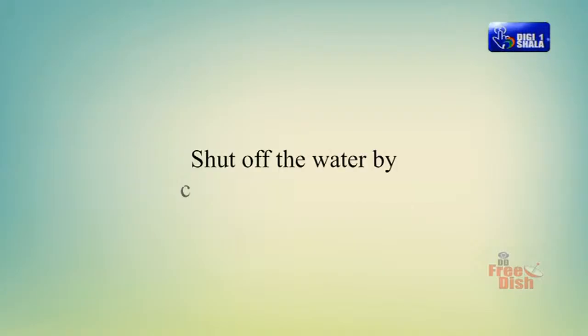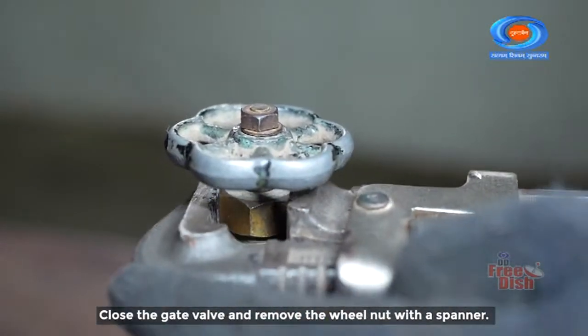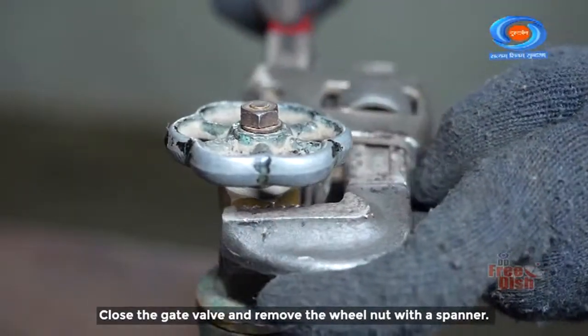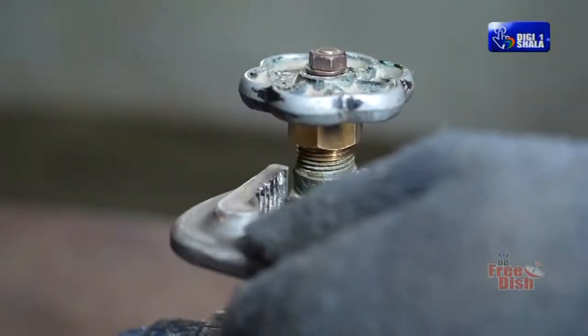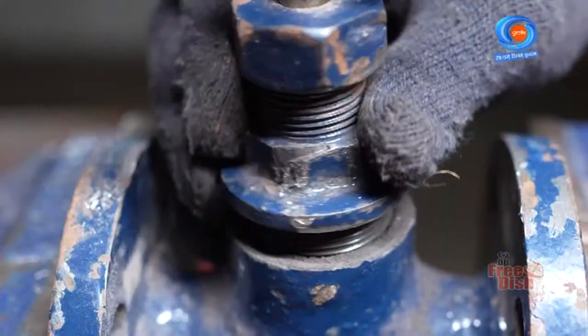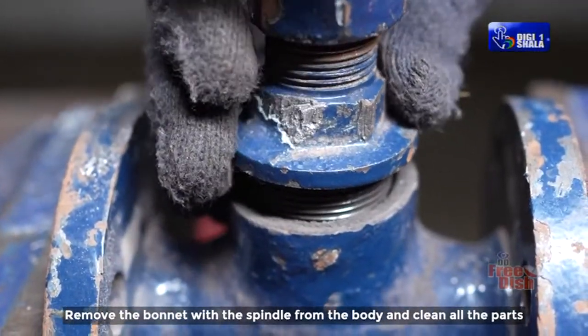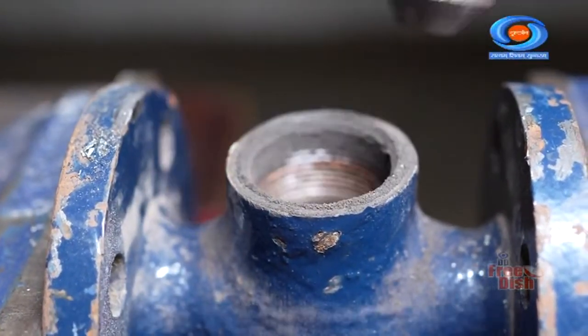Shut off the water by closing the main valve. Close the gate valve and remove the wheel nut with a spanner. Remove the gland nut from the bonnet. Clean out the old packing in the stuffing box. Remove the bonnet with the spindle from the body and clean all the parts.